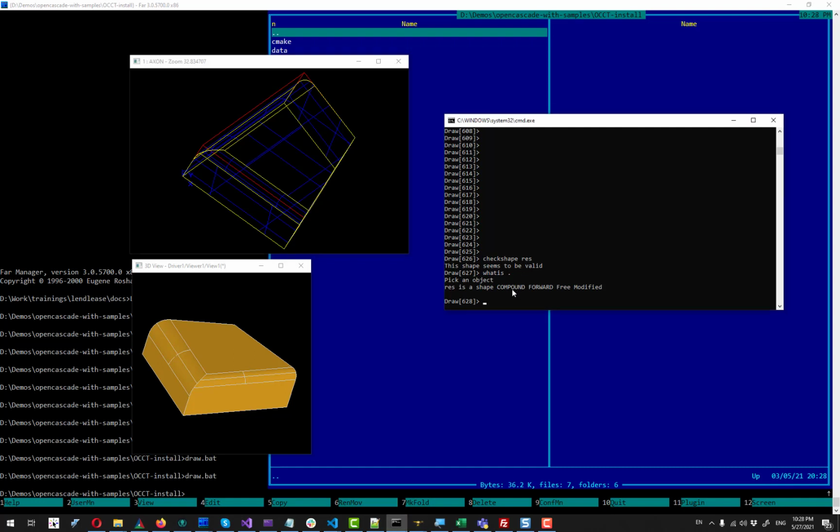If you say compound, then it's an indication that you have a sort of external container which might contain your solid, or it can also contain something like a set of faces, and this is not something I want to have, because a solid object is a more sound entity. A solid object puts some more restriction to your boundary elements, like you expect that you can compute a volume of your solid and all the faces of your solid are properly oriented, like you have all the normals of all your faces pointing outward the solid object, the enclosed volume of the object.